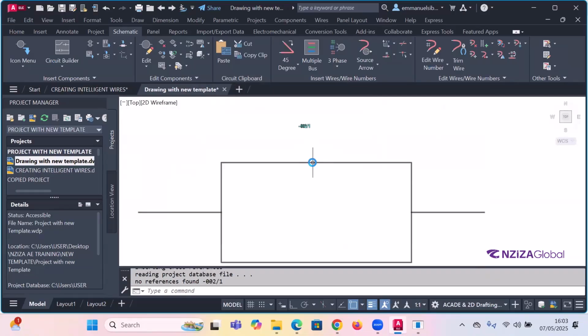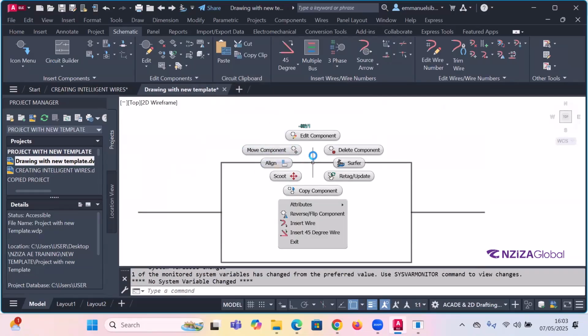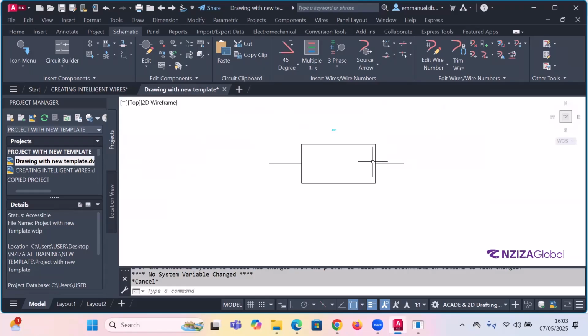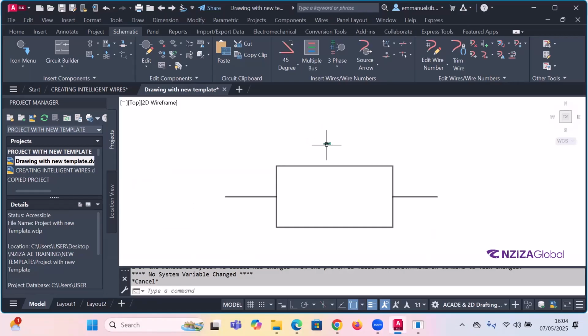You see that my fuse created from scratch becomes a component with this symbol. So I hope that in any project, when you try to find a symbol in a library and you miss it, you can create your own symbol from scratch and put your symbol into your project.